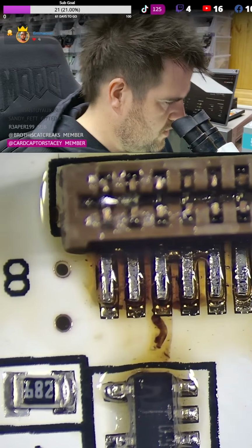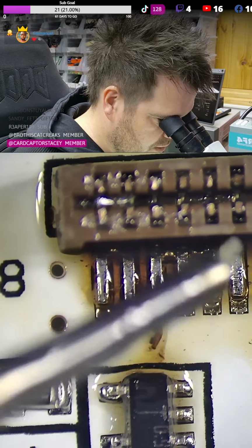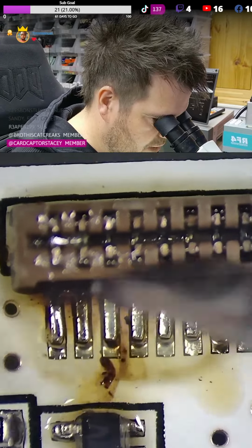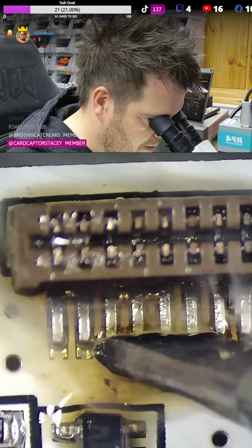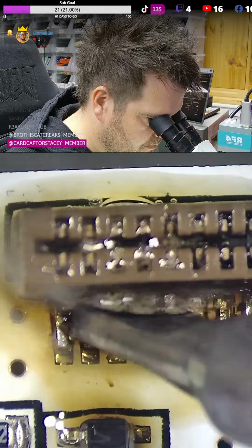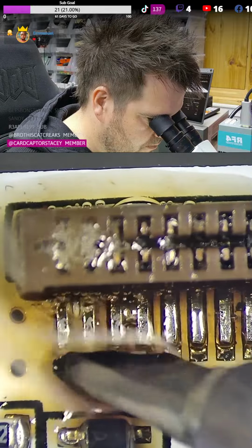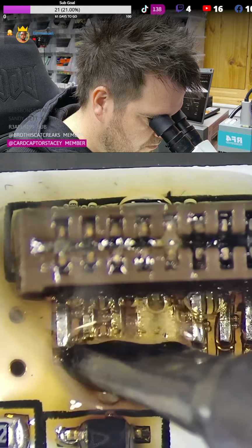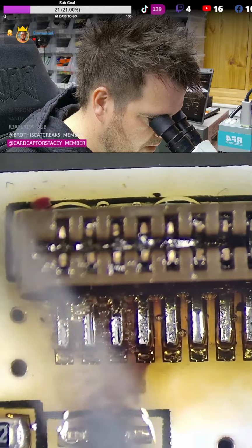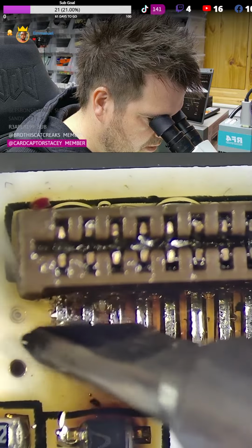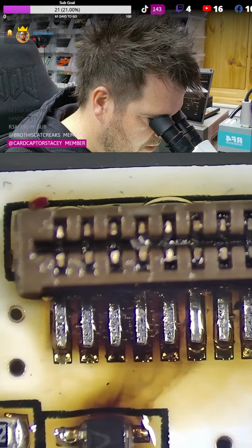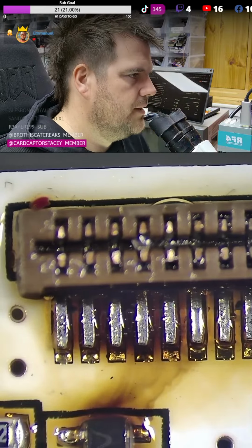And then you still see you've got a little join here at the top in all three. That's no problem, because now if you clean your iron and you don't have much solder on your iron, fresh flux and go back on it with heat, these should naturally flow back off now if you get them warm enough. And all of them did until that last one decided to go back on. Clean the iron, go back on. And I think that's now got them all.